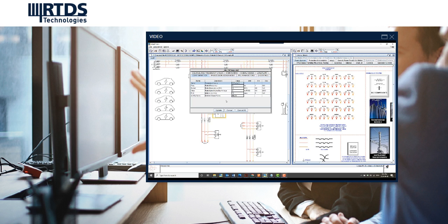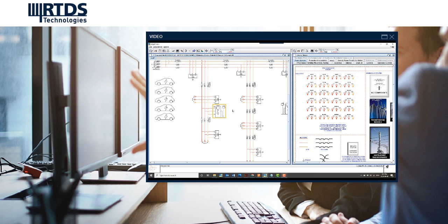There are 2 ways to control the reactive power for the EV charger. There's direct Q control by the user, and then there's the ability to use the reactive power for voltage control. And you can see that the source of that reference signal can come directly from the user in runtime or using a control word within RSCAD. Each EV can be connected to up to 10 different charging stations.